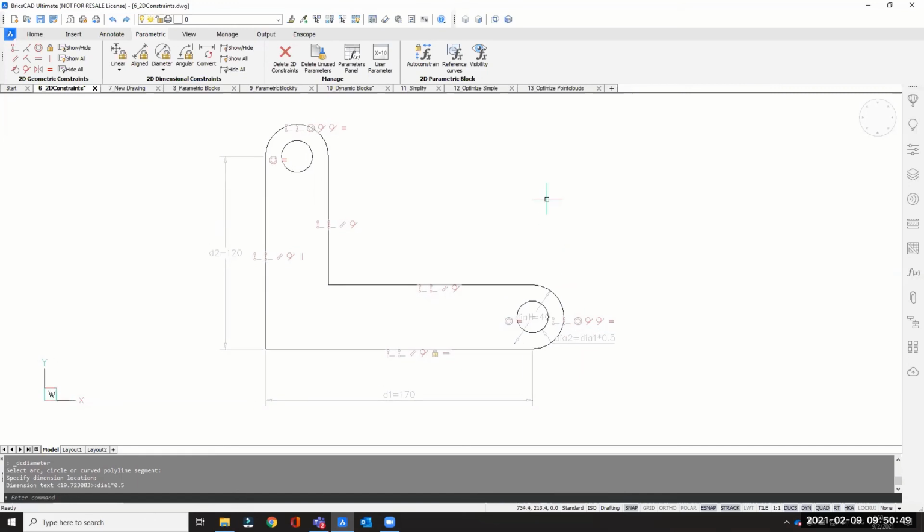Okay, so I think until this point would be fairly easy to add all these constraints. Just follow the specific constraints that we were talking about. It's all in the exercises. And after that, just add in the dimensional constraints. So we can change the dimensions of the bracket by the following variables. So D1 would maybe be the horizontal length, which is here. D2 would be the vertical length. And diameter 1 would be the width of the legs.